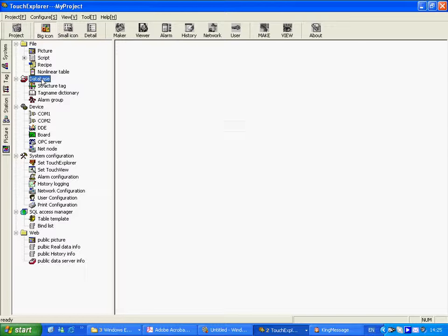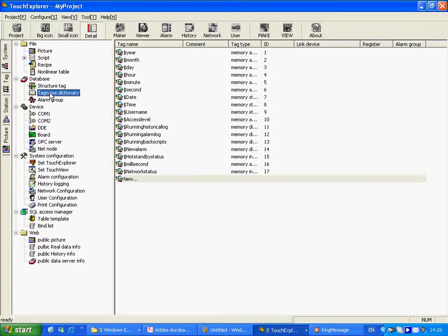The tags are displayed in the tag name dictionary, which gathers all details of every tag. Tag types within the tag name dictionary. The data dictionary is made up of tags defined by the user during a project and predefined system tags for a project. The tags can be classified into two groups, special and basic. Special tags include alarm window tags, historical trend curve tags, and any tag with a $ sign in front of it.